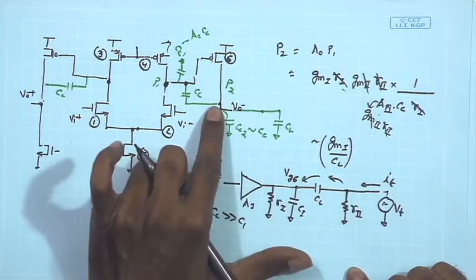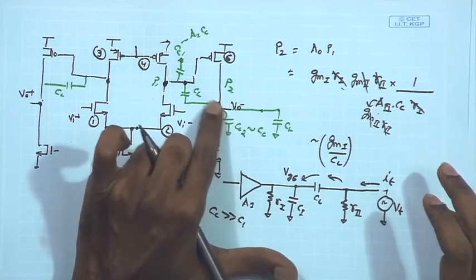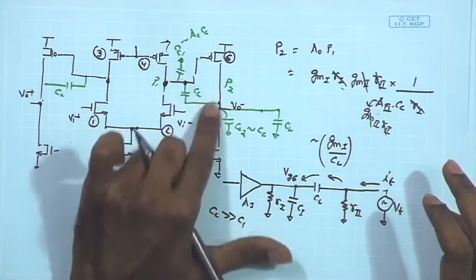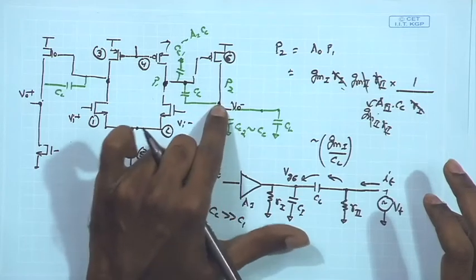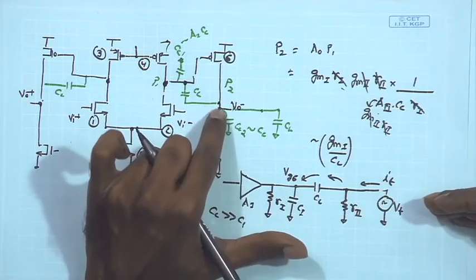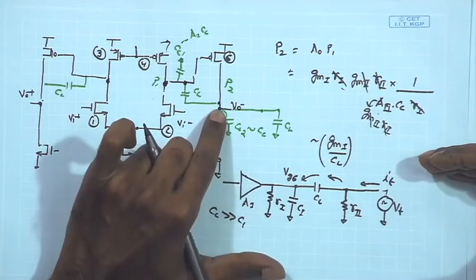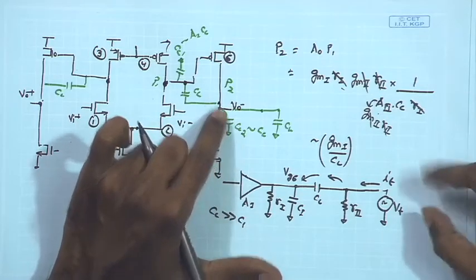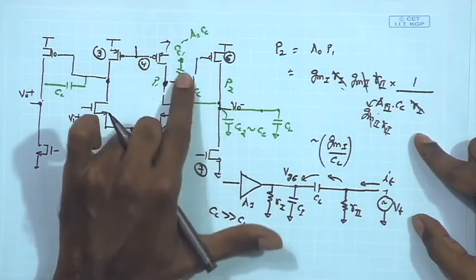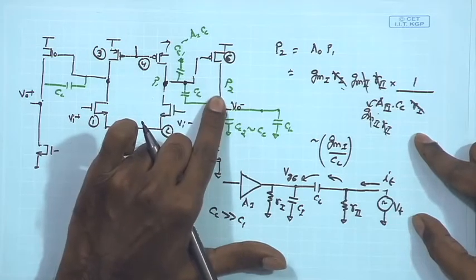So, the conclusion out of this is that we are having a reduced effective impedance at the second stage because of this bypassing effect provided by Cc at high frequency, which basically is going to push the second pole to a much higher frequency. Rather than having an overall impedance over here given by ro by 2, we are having an effective impedance at high frequency given by just 1 upon gm6, which is the small signal impedance provided by M6 when it is getting effectively short circuited, when the gate and the drain of the MOSFET M6 are getting effectively short circuited.